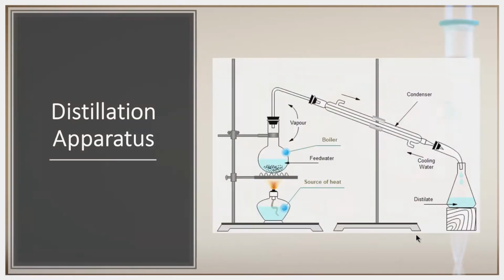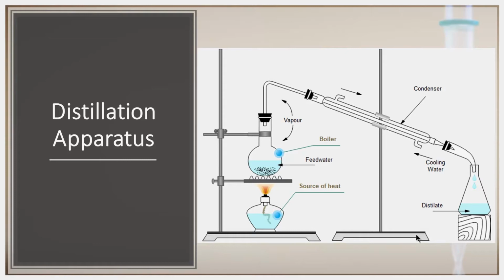Now, moving to distillation, it is a process of converting water from a liquid to gaseous form, and since steam is pure gaseous water, all the contaminants in the feed water are removed. As you can see in the diagram, a conventional still consists of a boiler or evaporator used to evaporate the feed water or distillant, and a source of heat to vaporize the water.